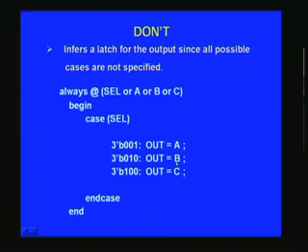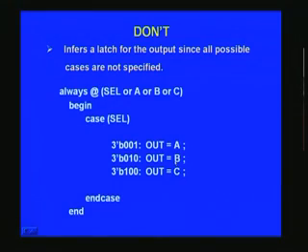So, the previous value was this. Now in the present case, let us say one illegal thing has come. So, it is not in any of this. It looks here, it finds no match. So, what can it do? What can it infer? It will be confused, it does not know what to do. So, what it will do is merely latch whatever was the previous signal as such. In this case it came from B, so it continues to be in that state, and this may be detrimental for your circuit design as such.